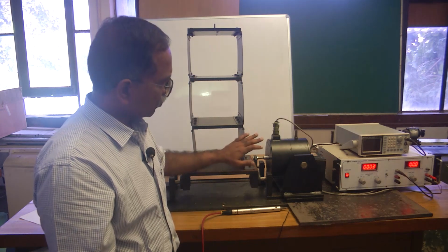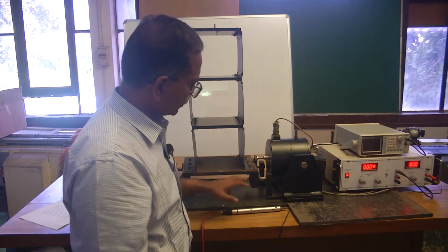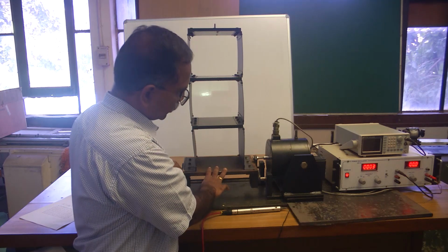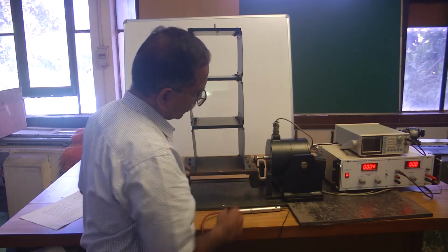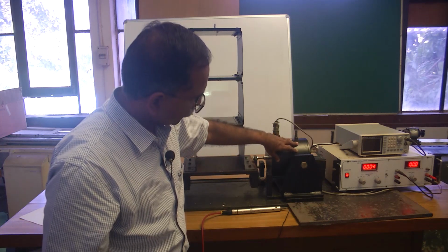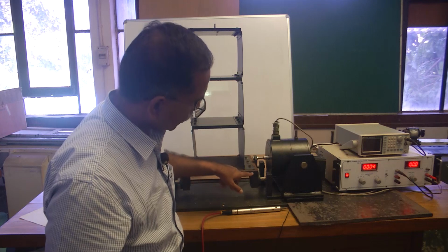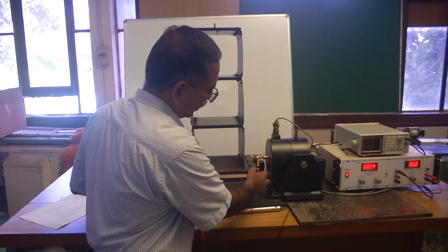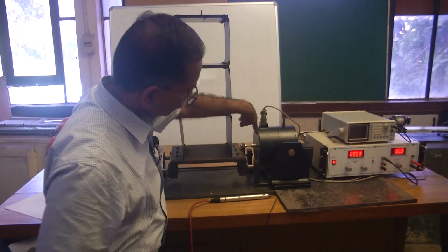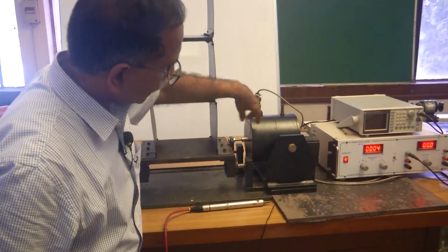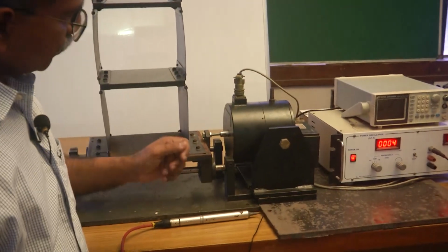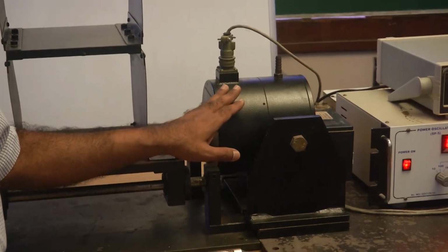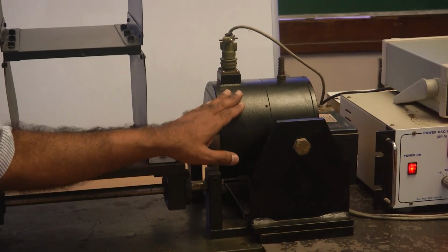So, for exciting this, what we are going to do is, this entire building is mounted on a plate here, which is made to oscillate using an electrodynamic shaker in the horizontal direction. So, as you can notice, this bottom plate is connected to the shaker through this connection, and the shaker's plunger keeps oscillating based on the frequency and amplitude with which the electric signal is fed to this exciter.